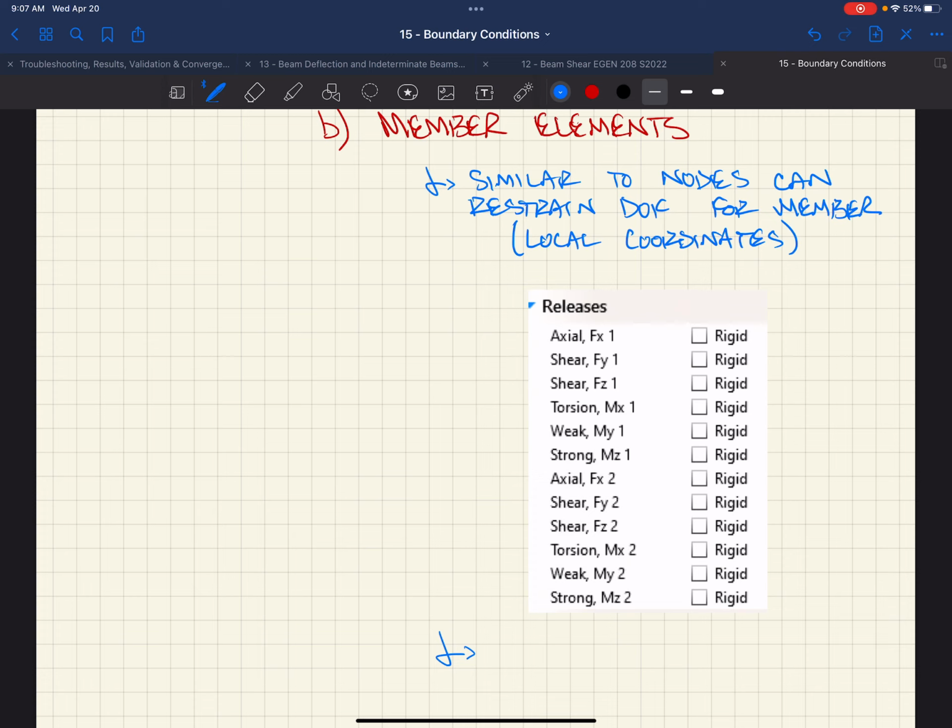Okay? I also mentioned this was one issue to look at with respect to our shear and moment diagrams. If you pick multiple beams that are, say, along the line on the east side or the west side of the tower, there's multiple members that line the whole length. Well, if you picked all of those members and had it show you the shear and moment diagram for some load combination, if the local coordinates opposed each other, then you get these huge jumps in the moment diagram, right? It wouldn't be this nice continuous thing. It would have to be all the members in the same local coordinate direction. Otherwise, you'll get weird stuff going on.